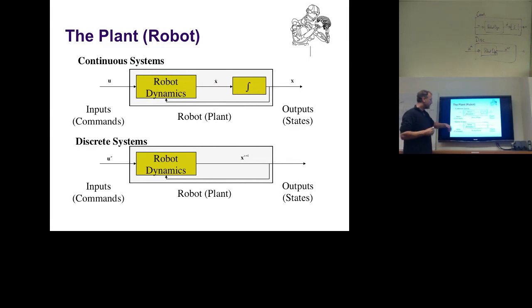Okay, yes. And importantly, I should mention, I forgot this before, we always have feedback of the state back to the robot box, since the robot dynamics obviously has inherent knowledge of where it is as a physical system, so the state is just inherent in the system. So discrete systems omit the dot variable by directly going from where I am currently to where I am at delta t in the future. So there's always inherently some kind of a delta t time step. Very important.